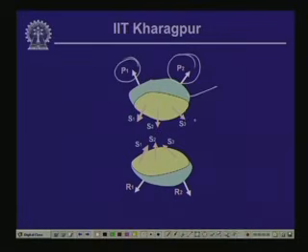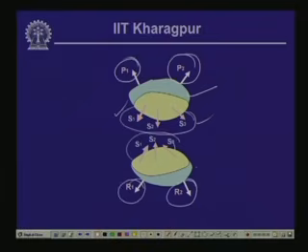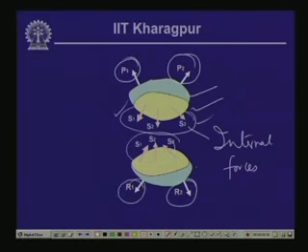Now, when we have taken a cut of the body and separated it into two halves, we can see that some forces are generated internally, which we call S1, S2 and S3. The other half will also have reactive forces, and these forces will be equal and opposite in nature, because in statical form they are in equilibrium. These forces generated internally to equilibrate the external loads, we call internal forces, and these diagrams are also called free body diagrams.